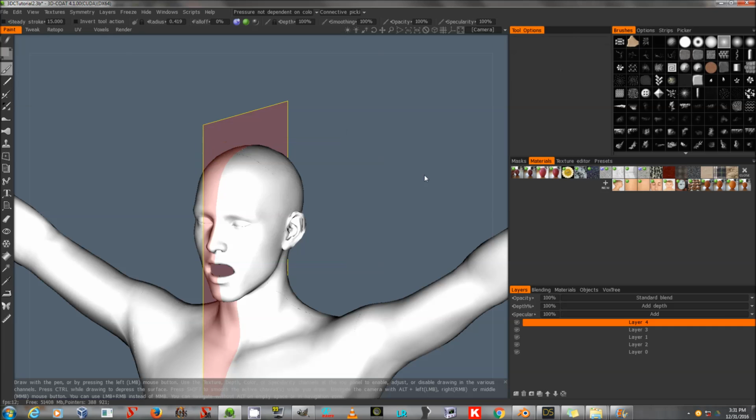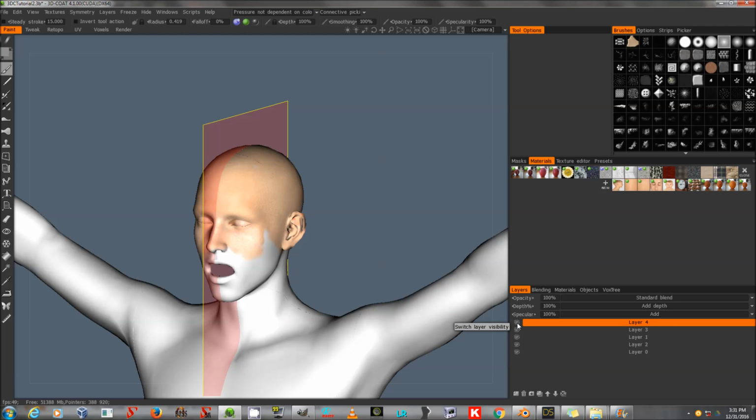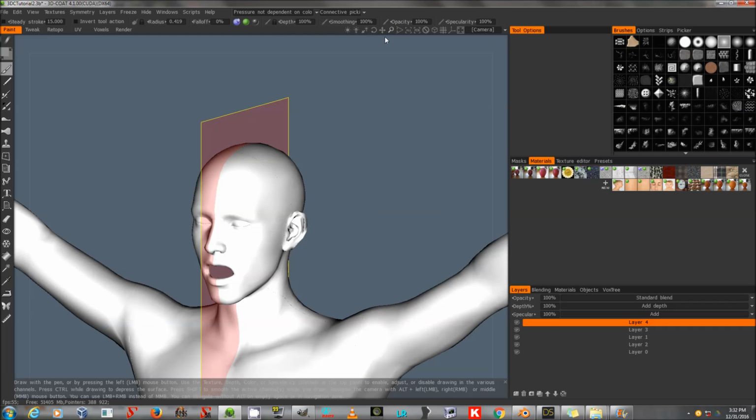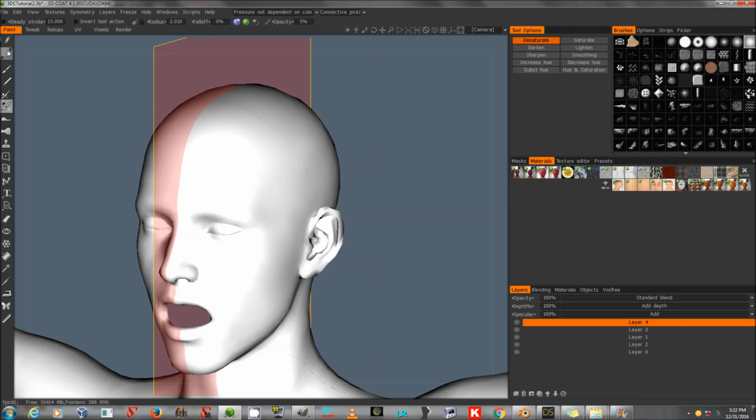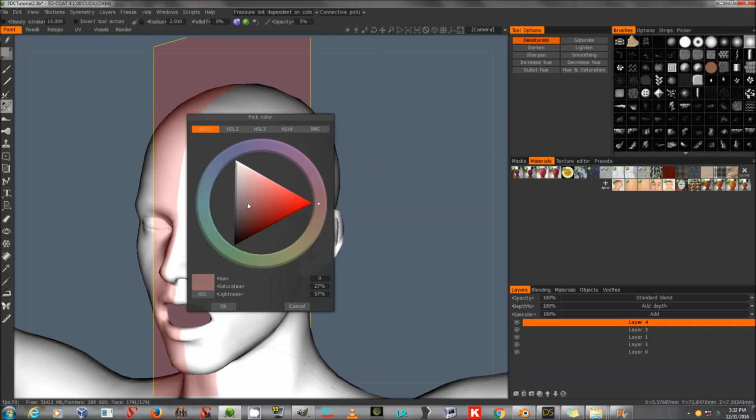So when I go back to Paint, my textures are hidden, but if I hide that top layer, I can see the body texture again. There we go. And when I do the translucency, I want to start from a gray texture and then paint darker areas or veins or lighter areas onto it. So if I want to have little blue veins, I can hit Paint there, give myself a blue base texture using the color wheel here.